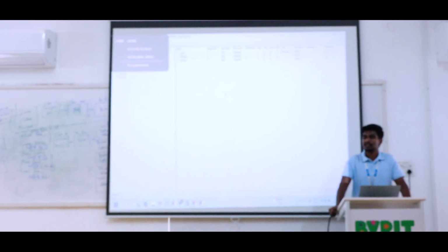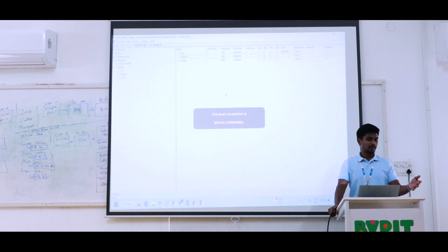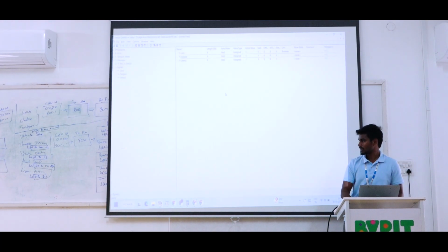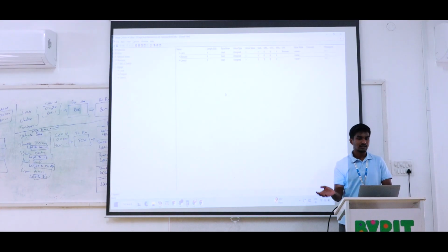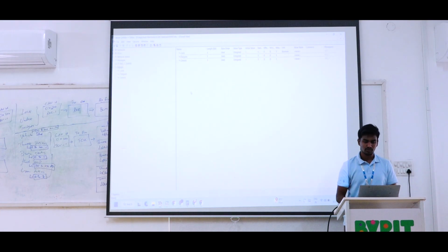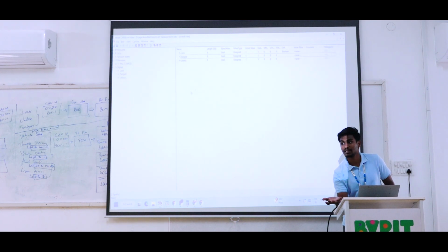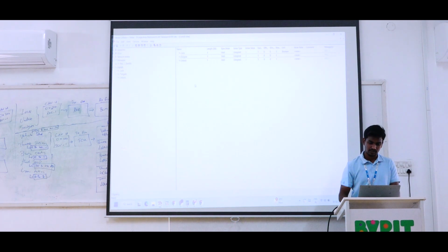So for mapping of messages, we can set the mapping for the transmitter and the receiver. We have faced some issues in signal creation and mapping from one ID to other ECUs. So I will create one more signal now.